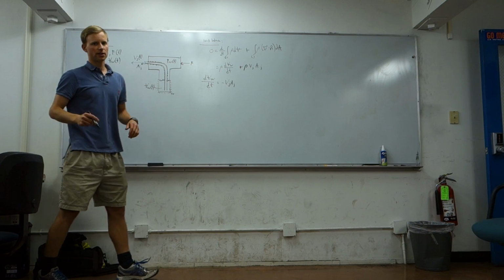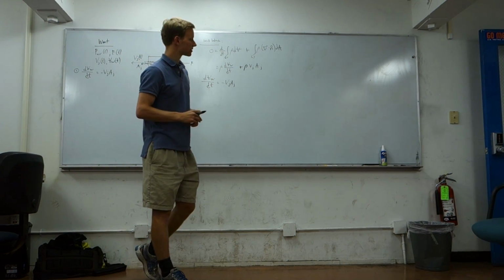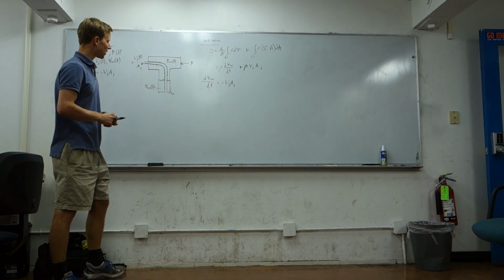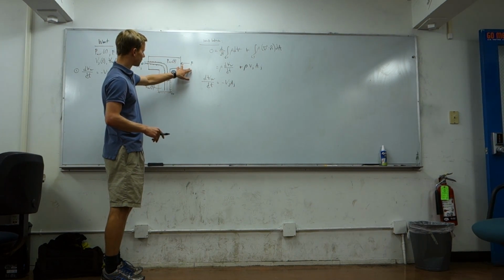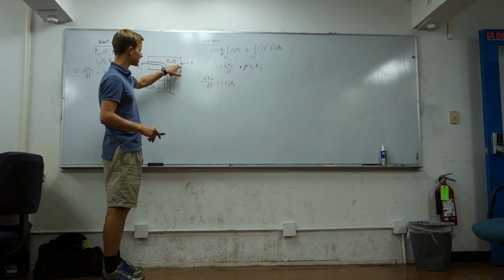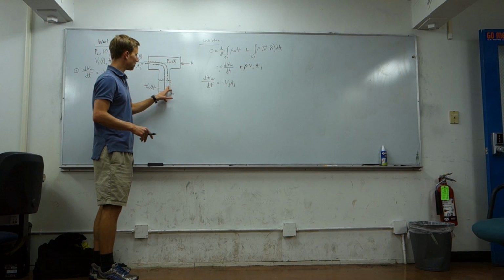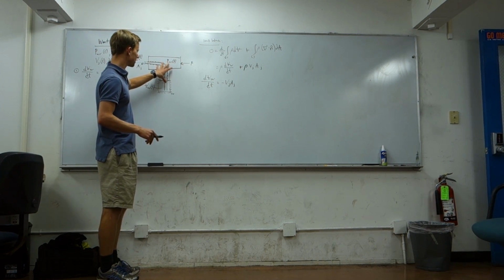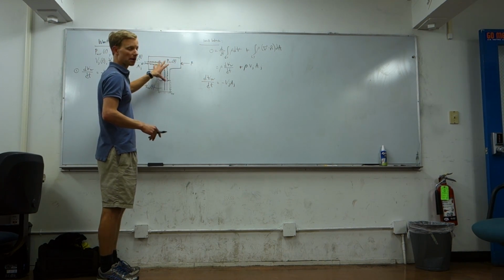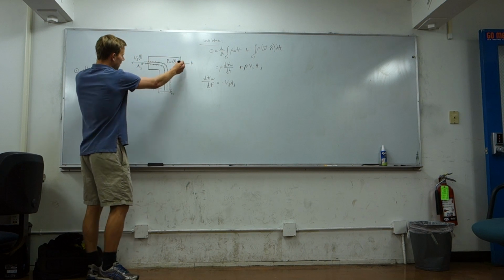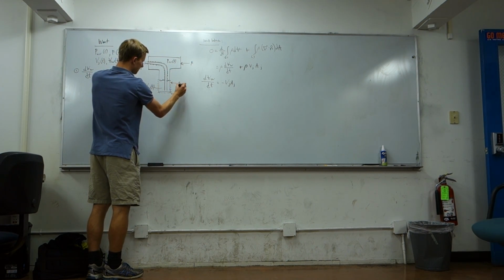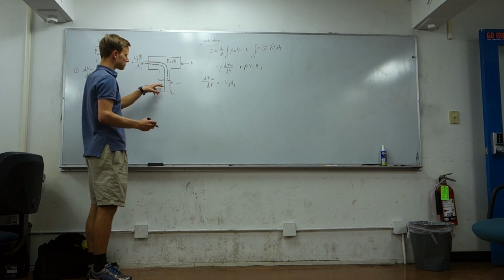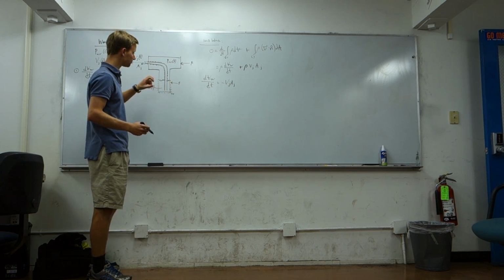Next equation we might think to use is maybe momentum balance, since we know we're going to have to solve for that force over there. And before I can start with momentum balance, I just want to explain one thing about this force, in that right now I don't have it touching my control volume. However, this is a rigid container, so we're not going to be caring about moment balances. So I can apply this force anywhere along the side, and I will just move it over here for simplicity. This is just because I chose my control volume to be just the water.